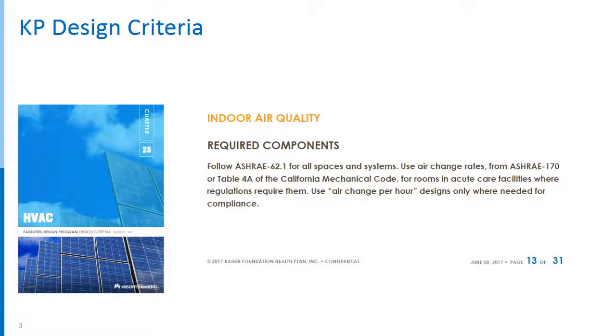And so Kaiser standards say to favor the energy method. And this has actually been our standard for a while. I started in 2011. This predates me. And I'm not going to pretend that there was a great reason for it, before my time. It's just that it's cheaper to build medical office buildings using the energy code method. You do return plenums and standard rooftop units, etc. Under the air change rules, you get bigger systems, and sometimes you duct the returns. You have these pressure relationships to worry about. So it's just more money.